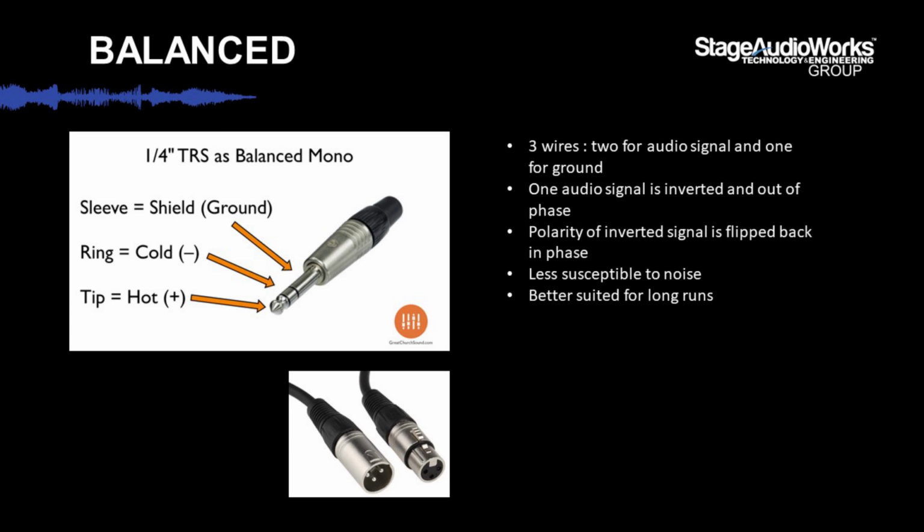If I can jump in, Nathan, I think it's important to look at what's on the other end of the cable. Ross also mentioned the insert socket. That TRS jack is also used for the insert, with the ground and then the send and the return as your tip and your ring. So is it stereo? Is it balanced? It depends on what the cable is connected to.